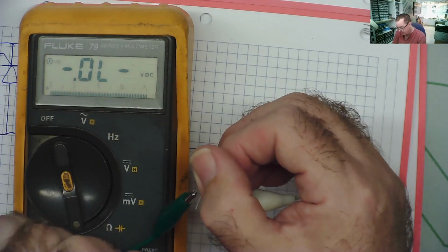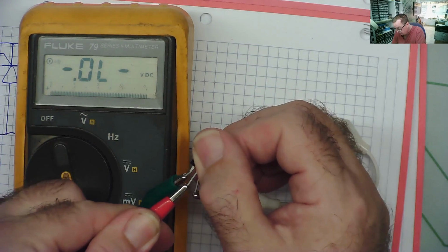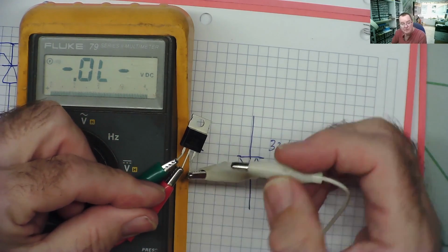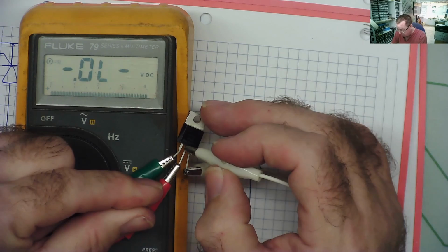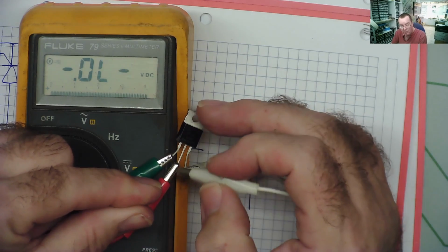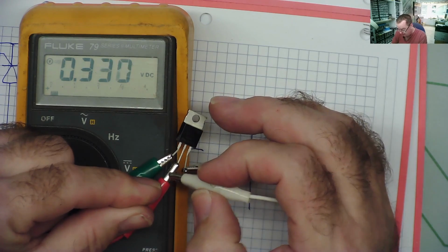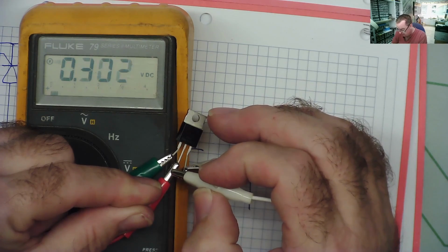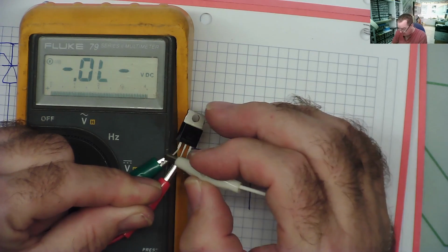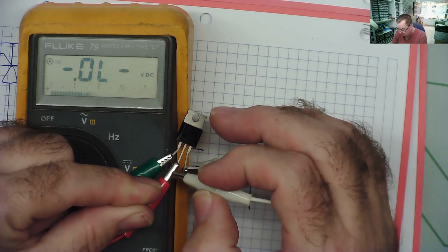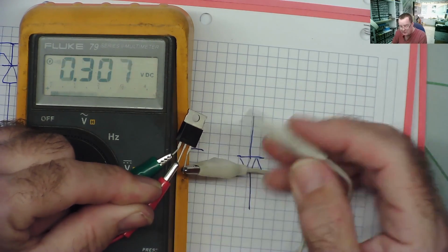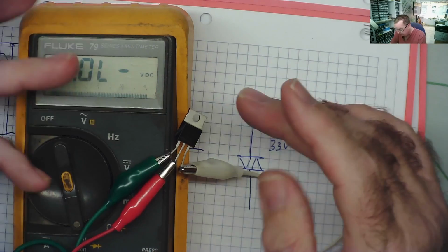And we'll reverse the polarity of these two. Okay? Now what happens? While it's now switching on, effectively when I'm on the red wire, the green wire isn't, so it's reversed. Before I was touching the green wire on this terminal, switch it on. Now I'm touching the red wire. So that's a pretty good test for a Triac.